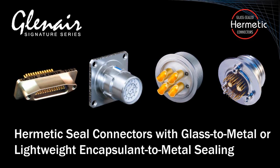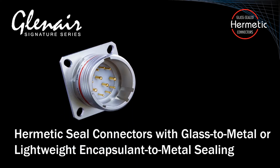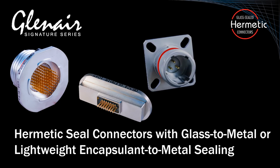Hermetic seal connectors produce a condition commonly referred to as airtightness and are fabricated via a glass-to-metal or lighter-weight encapsulant-to-metal sealing process. Both technologies deliver outstanding airtight performance for high-reliability applications and may be specified in a broad range of both circular and rectangular connector packaging.